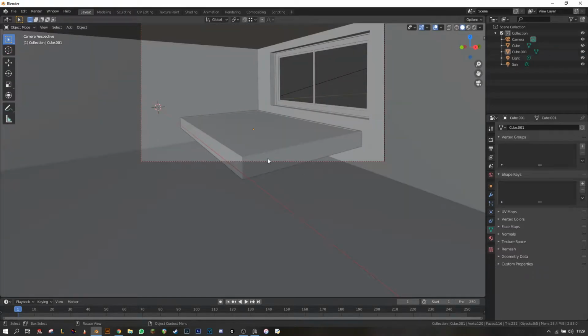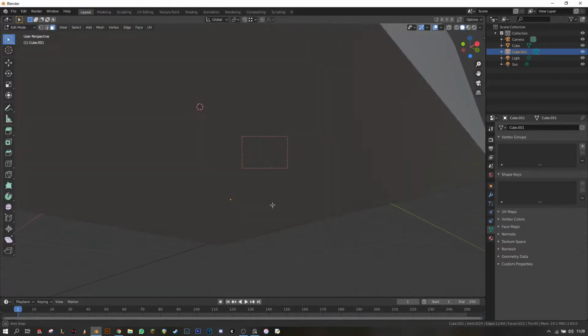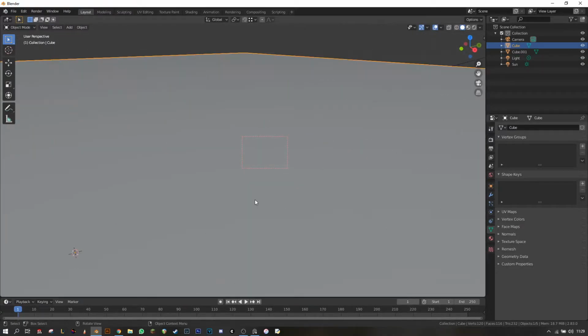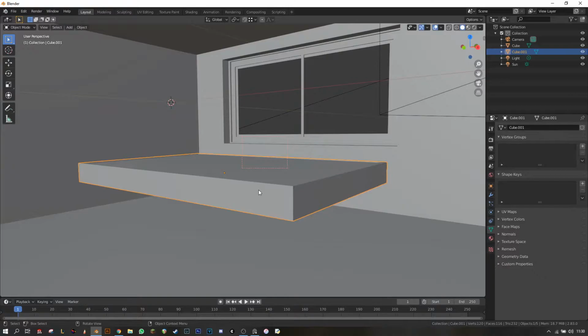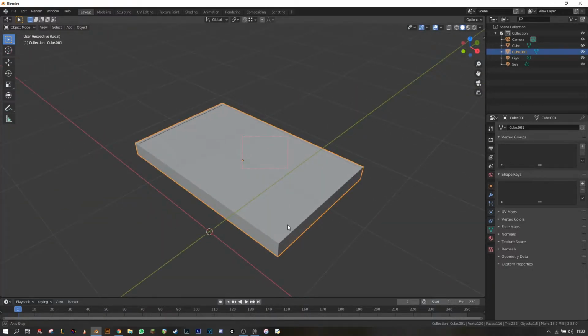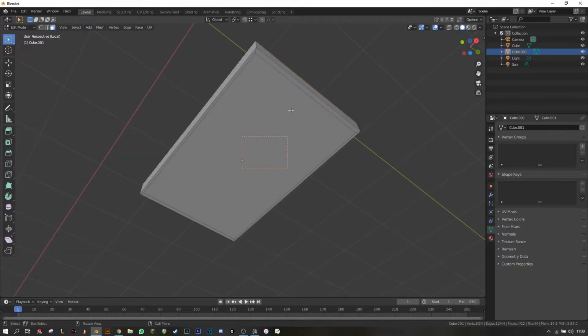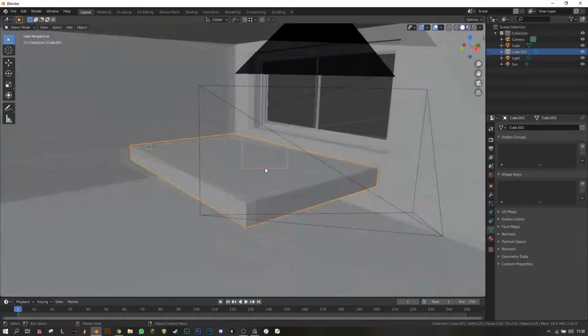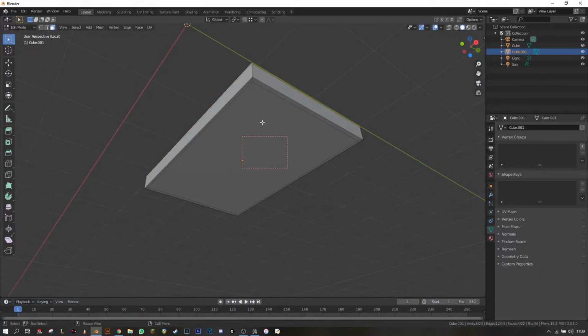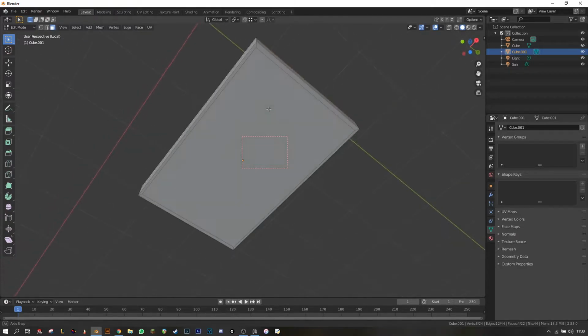It's looking quite good. Now, if you want to be able to see the bottom, obviously it's a bit of a pain that this whole room's in the way, and you can select it and hide it, but I find a much easier way is if you're working on one thing, if you press / on your keyboard, it'll go into a highlight view where you can just see the object you're working on, and then you can work on it, do whatever you want, press / again, and you'll come right back to where you were. So it's really helpful for when you're just doing a little bit of editing. You don't want to have to hide every object, and that's obviously even more important when you've got loads of objects in your scene. You don't want to be doing that every time, so it saves a lot of time in the end.